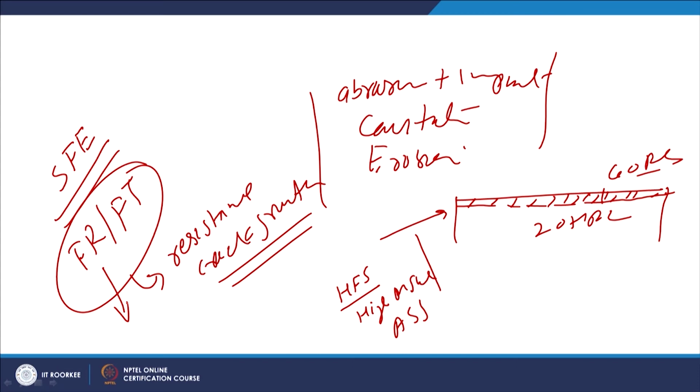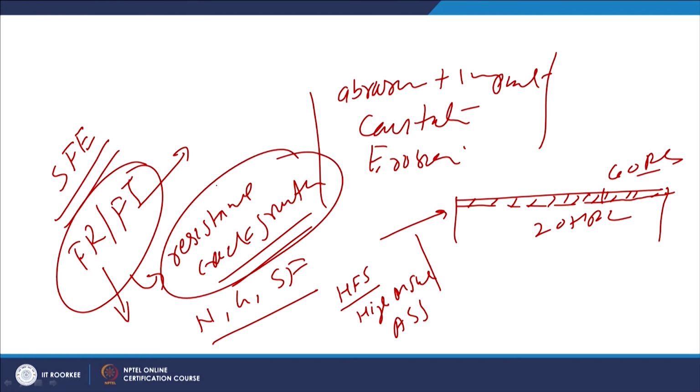Fatigue resistance is about the resistance to fatigue under dynamic load conditions, wherein first nucleation, then growth, and then sudden fracture of the component takes place, while fracture toughness indicates the resistance it will offer to nucleation and then growth of a crack. So, wherever such situations happen, good fatigue resistance and fracture toughness will offer good resistance to the removal of the material.